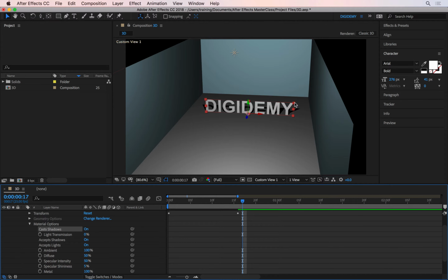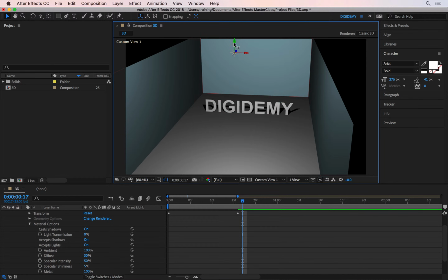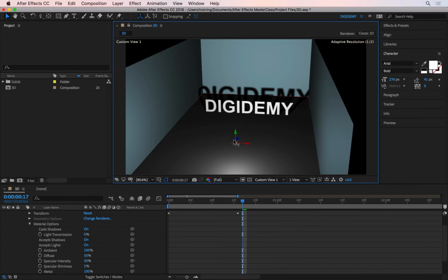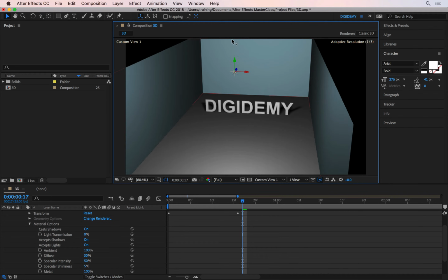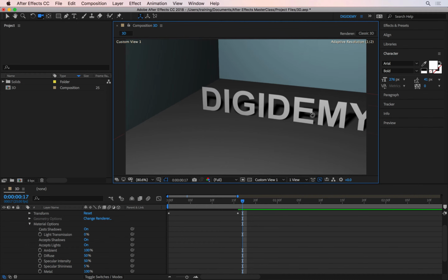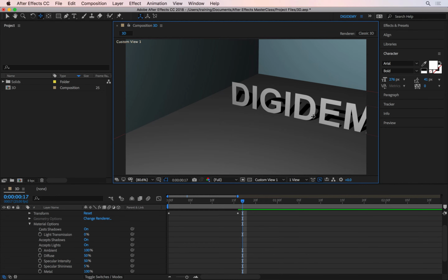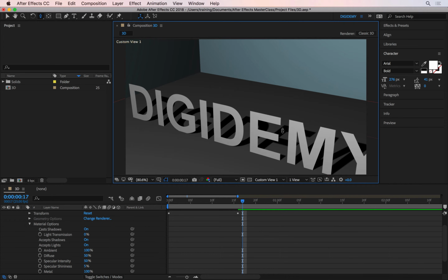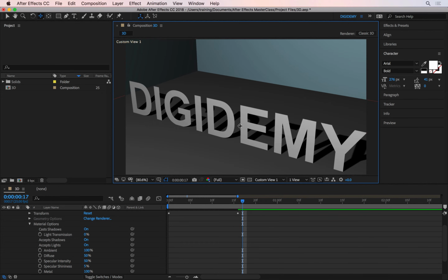the floor. Now, depending on where your light is, so if I select the light here, depending on where the light is or how high it is, the shadows will change appearance. If I drag this further down, you see you'll have longer shadows. As I drag this up, you'll have shorter shadows. Now, if I zoom in here a bit more, so if I just use my camera tools to zoom in, and then maybe orbit around a little bit, and then maybe push this to the side, and then push in, there, you'll notice that the shadow has no diffusion, so it's quite sharp.